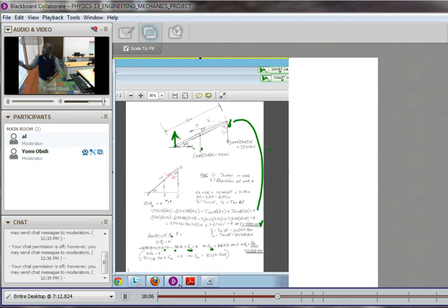Remember, we want F. We want the force acting here in the boom. We want that force that's acting at that point. So that force is given as F sub AY over sine 45 degrees, and that gives us the reaction at the boom. So that's how we do that, and we get the forces that are explained in each case. We will now look at another example of the representation of these forces.